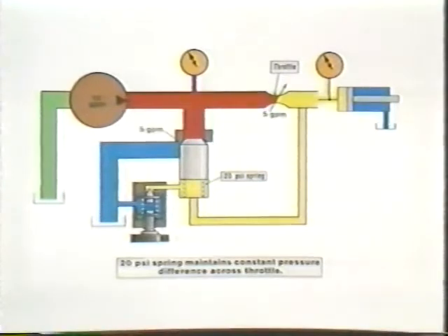A bypass-type flow control valve is used only in a meter-in circuit. It will not hold back against overrunning loads, nor can it be used in a bleed-off function. So this valve is limited to one application, meter-in, but it has an advantage.